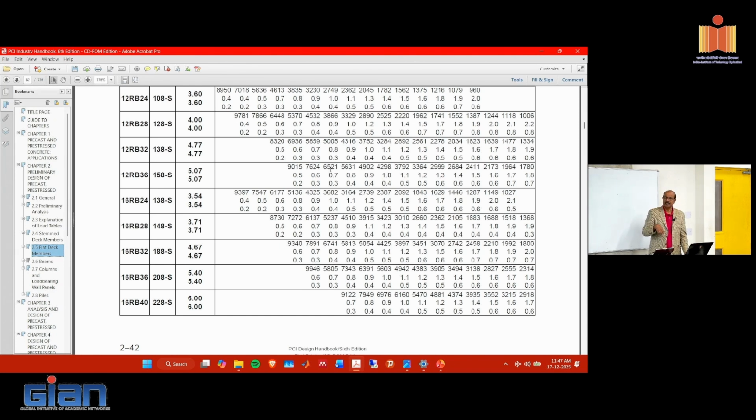And especially cast in place, in the US, is very expensive because the labor is expensive also. And when it comes to this particular construction, the cost is very competitive because they de-skill the labor, as they call it, right? So they will have different crews, as I mentioned. Somebody is tying reinforcement, you train them once, they will just tie reinforcement forever, right? So they don't have to do other stuff. That's their responsibility.